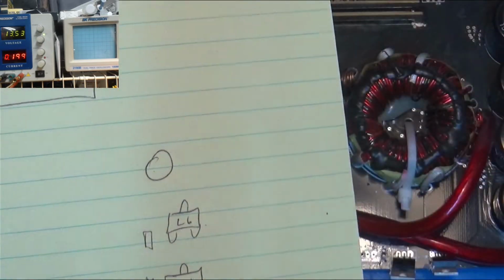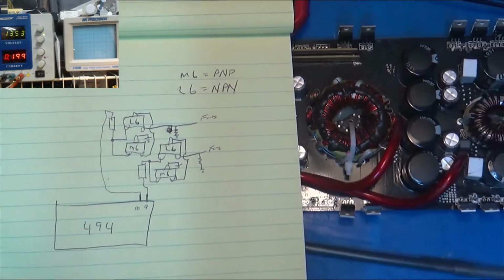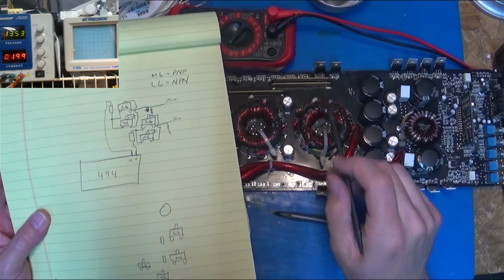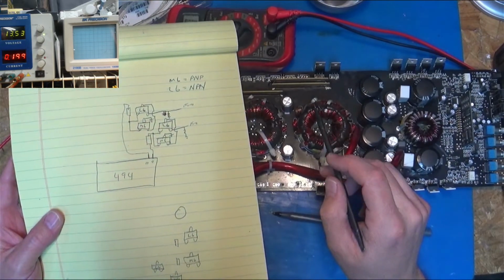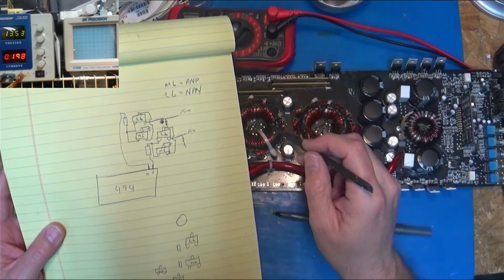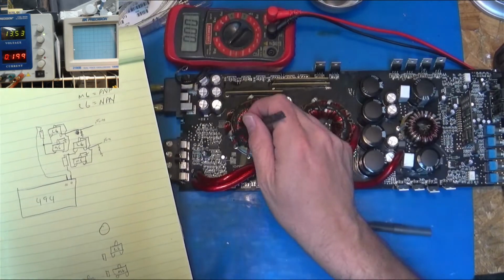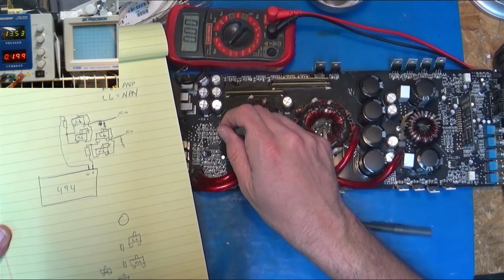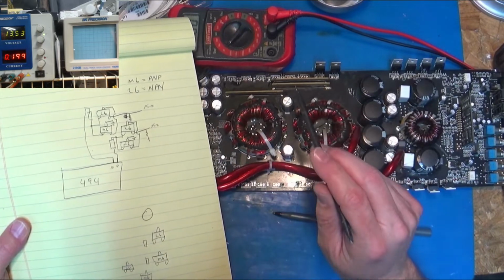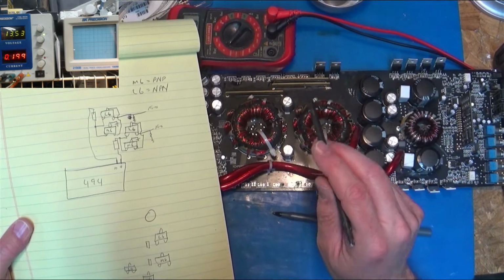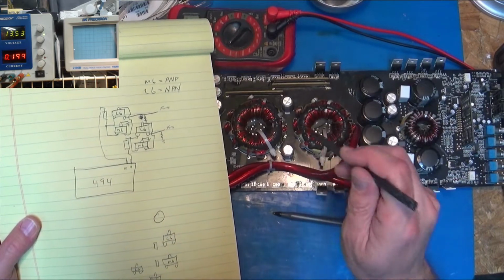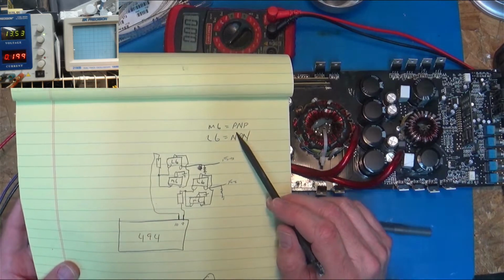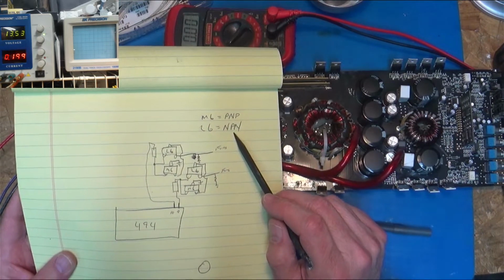So I figured those out, based on what I could barely see on the schematic, and then using the same method I did in my one video where we go over the power supply, how a switching power supply setup works and how you determine those. If I somehow figure out how to do it well, I'll try to link that video at the end of this one, or I'll put it down in the comments, worst case scenario. But I figured out that M6 is the PNP, L6 is the NPN.